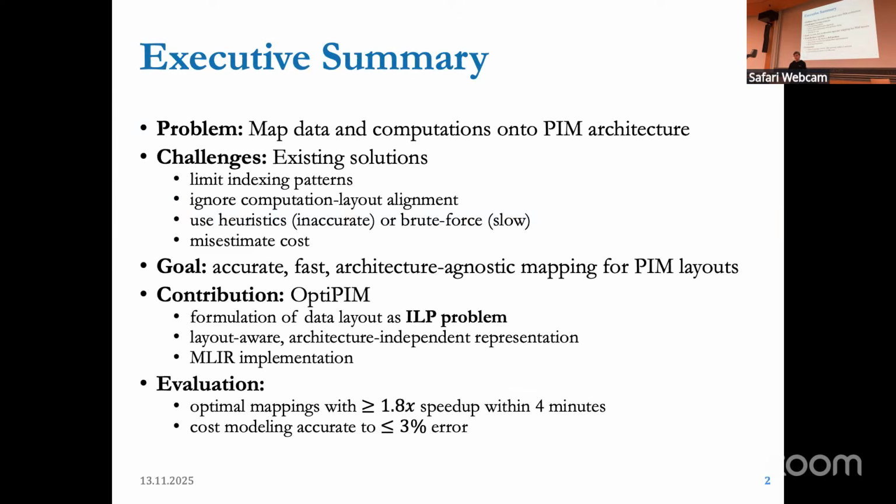OptiPIM tries to solve the problem of mapping the data and computations that we have in some programming language onto the respective PIM architecture. Existing solutions often limit indexing patterns, ignore some specific alignment that PIM requires, use heuristics, which makes them quite inaccurate at times, or use brute force, which makes them very slow at generating these layouts, or just misestimate the cost.